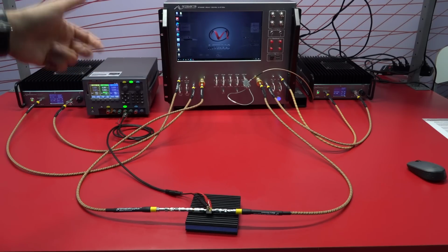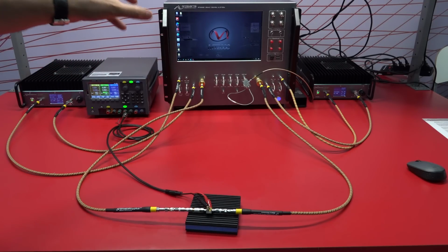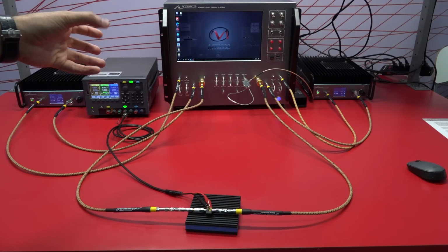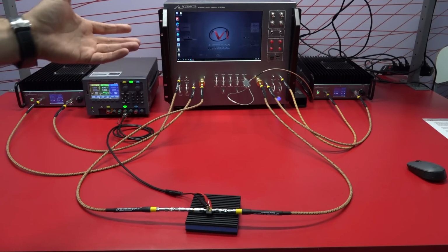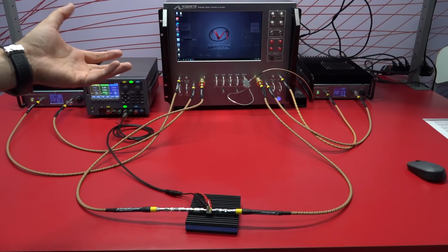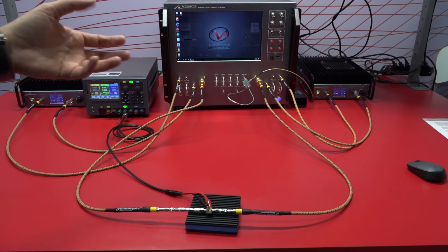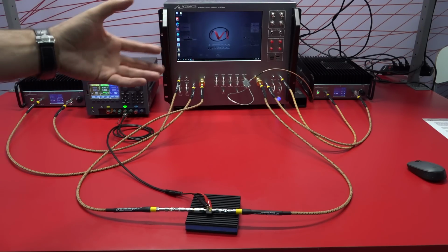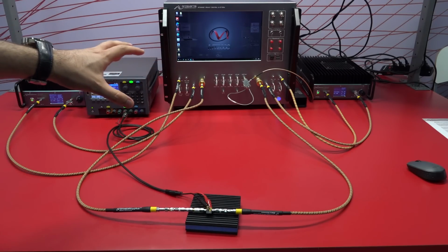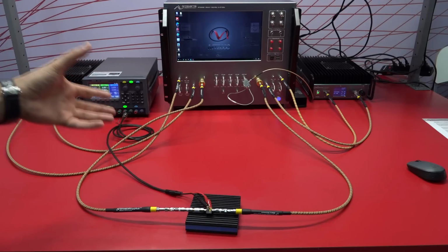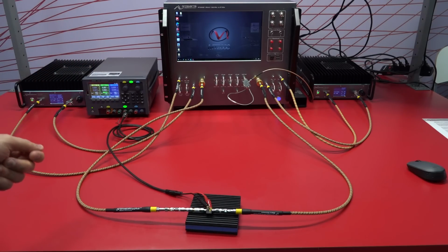can also measure things like compression, ACPR, and because you do have that 1 gigahertz modulation capability, you can now look at your constellation across load pull conditions, which is ultimately at the end what you're really looking for, because that's going to determine the signal to noise ratio of the entire link across those load pull situations. Everything together, super fast, all in under one. Of course, when you own every piece of the system, you can make it super optimized, but then it's a one-stop to make all these measurements in one go.